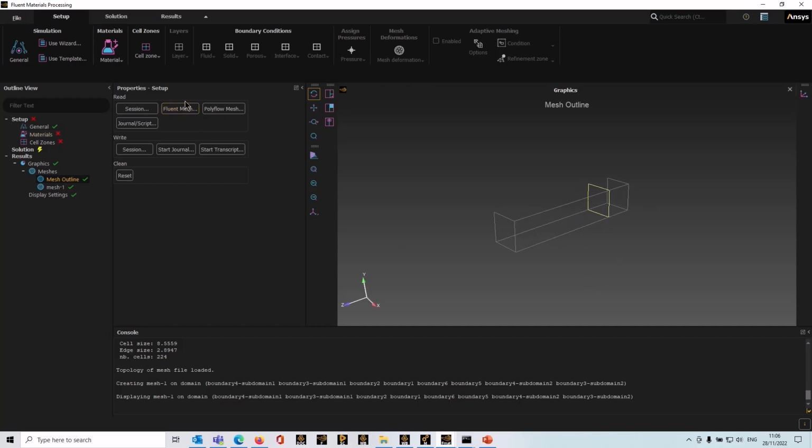When we start this simulation, you can set everything up manually, but there are a couple of features here under Setup Simulation. We've got something called a wizard and a template. They both set up most of the elements of the simulation process for you so that they insert all of the right tasks in the outline view.